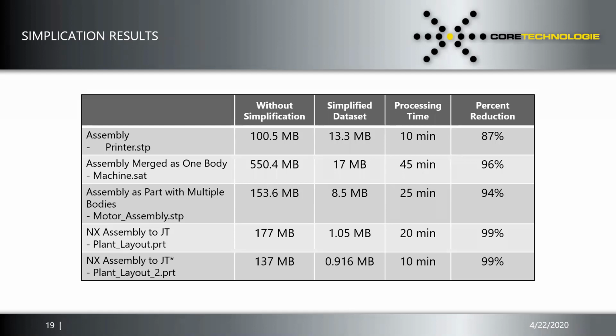So we actually added a tab into the top where you saw the right-click solution said Simplify Shareable. Well, we had the Simplify Shareable tab inside of Teamcenter where, if you have the item selected, you go up there, select that tab, and choose the level of detail. What's really interesting is we can have a couple of different customized scripts, as in a simplification script specifically for internal use. So you can have your whole master assembly, but have a lot of simplified models. Then it reduces that file size.